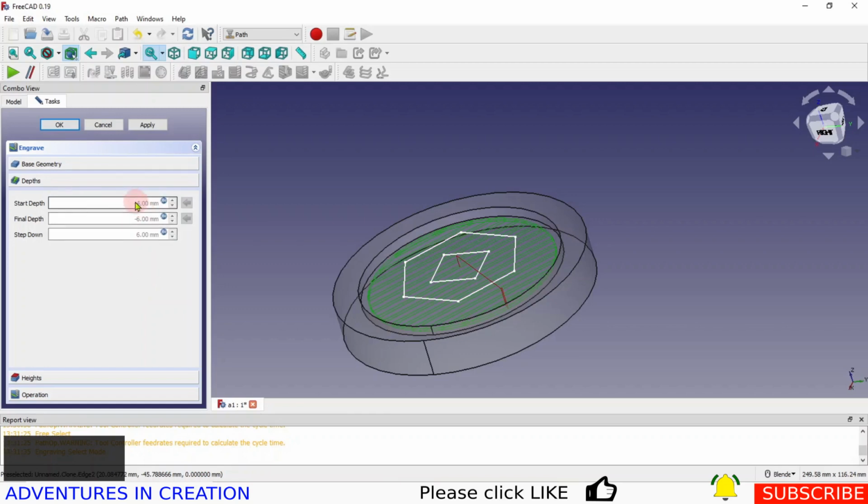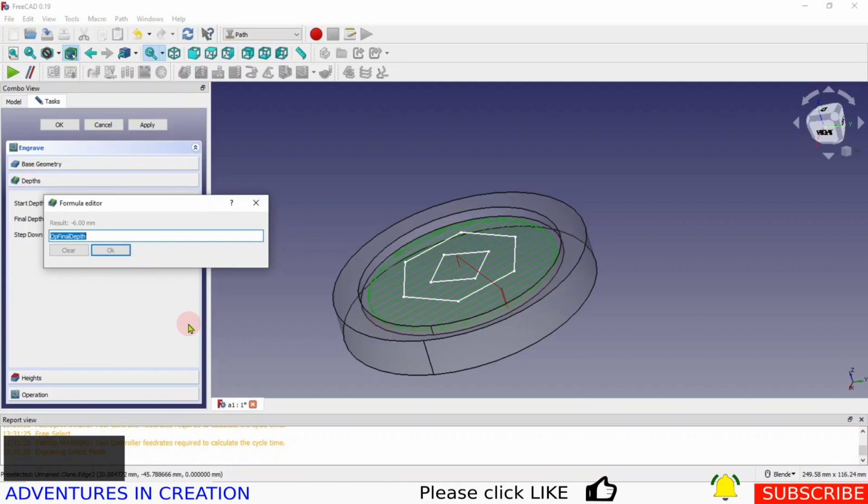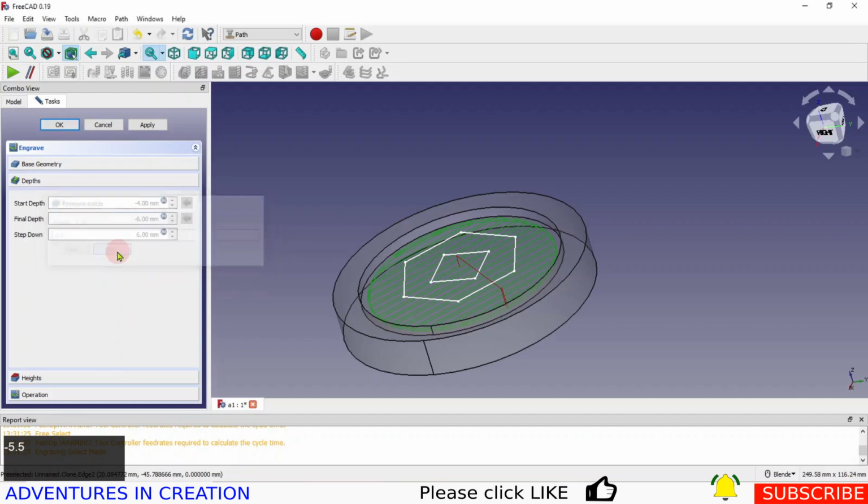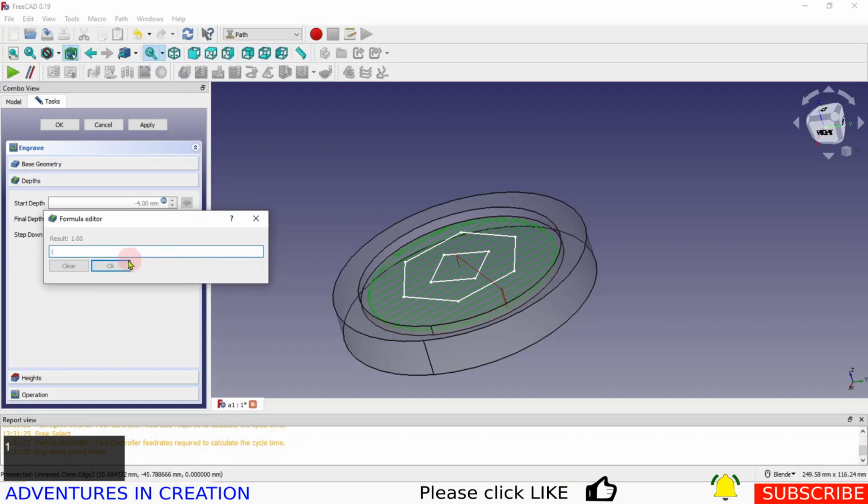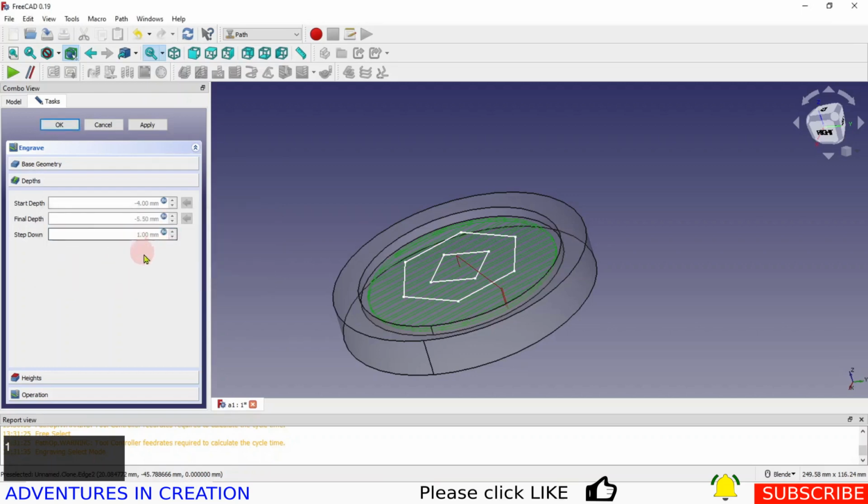Now, one thing with these dimensions that you put in here, sometimes they don't update right away. You have to click somewhere else for it to update. So I don't know if you saw that with the 4 mil one, but let's do it with the -6. So I'm going to go in 1.5 mil deep. So I'm going to say -5.5. And when I say OK, you see it's still on 6. But if I click here, then it changes it to the -5.5. And then with my step down, I'm going to make that 1 millimeter. And so that will be 1 millimeter. So we'll have 2 cuts basically for our engraving.